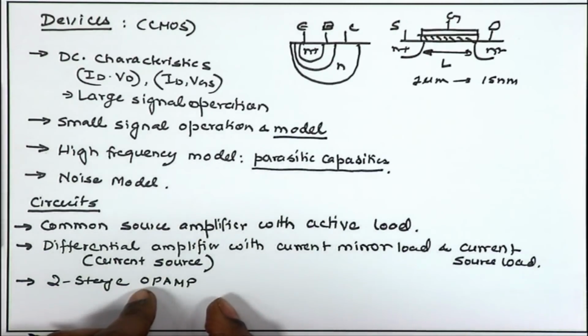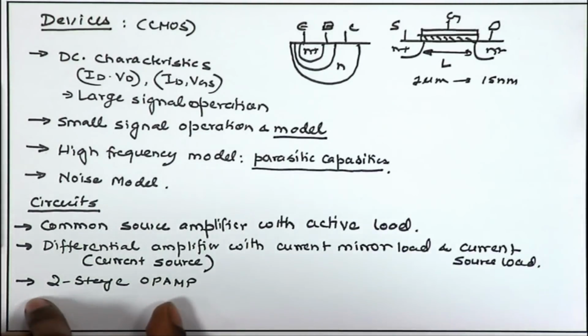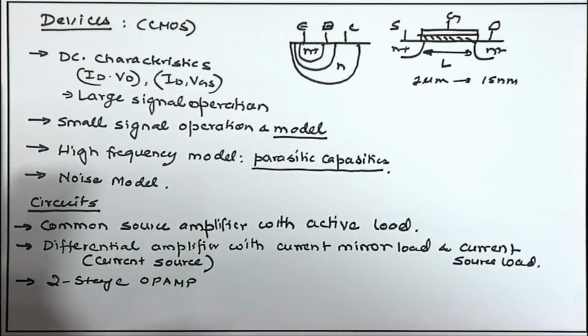I need to talk to the digital person, the DSP engineer, who is giving me the specification of the bit resolution required for extracting more sophisticated, more hidden information from the signal, and I have to address that need. That in a way has a feedback and tells me something about the specifications. So, the first set of specifications comes from the signal itself. What is the frequency content of the signal, what is the noise content, what is the amplitude of the signal, whether the signal is stationary, whether it has some dynamic offset, whether the baseline is fluctuating. All those considerations define my front end design specs.